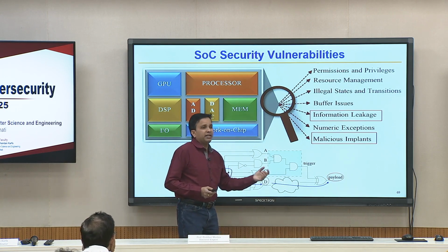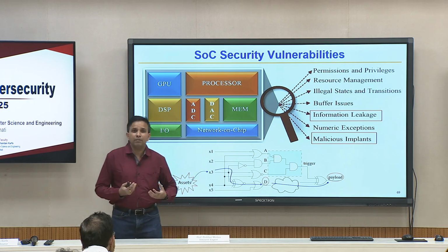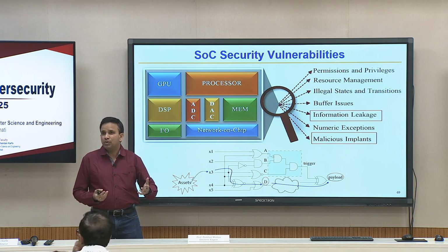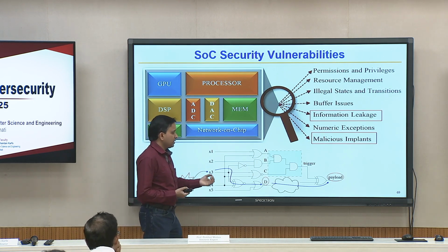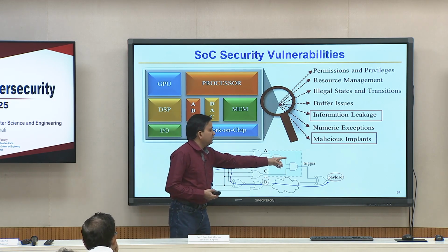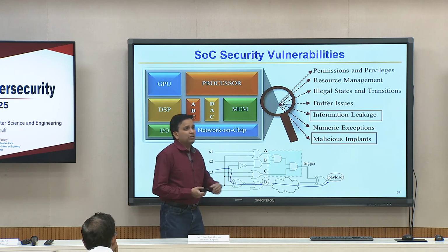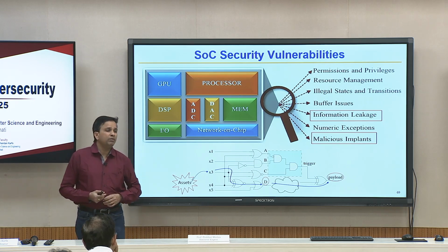There might be an if statement that stops it. That if statement might say if you are a privileged user, then something is supposed to propagate. In normal execution mode, the privileged user variable is supposed to be 0, but whenever you as an attacker want it, the Trojan will make that one 1, although you are in user mode, that variable would be flipped to 1.